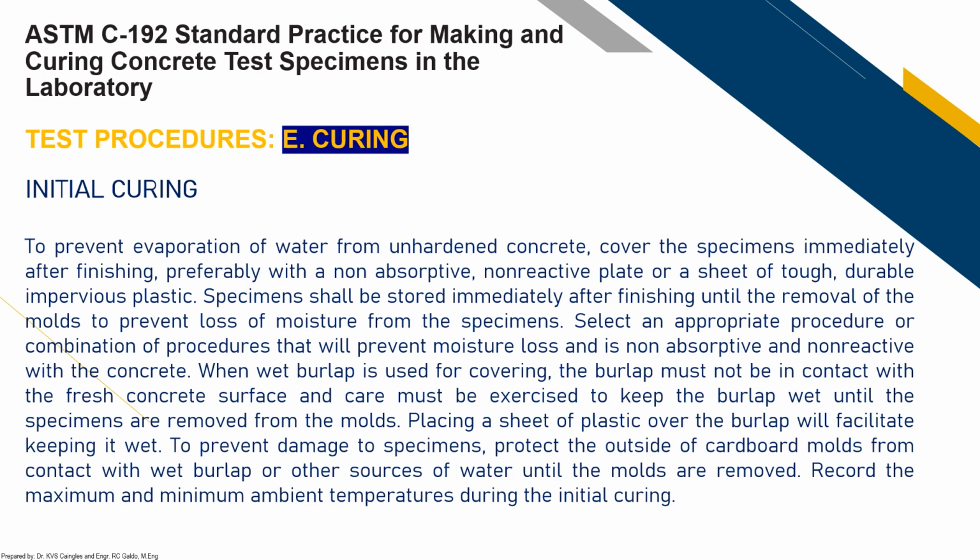Okay? So after the concrete is mixed, deposited in the mold, consolidated and finished, we can now proceed to the next part of this standard practice, ASTM C192, which is the curing of your concrete test specimen. When you say curing, there is initial curing and also final curing.